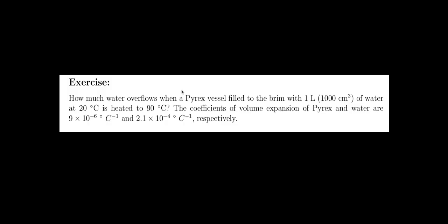Okay, so this exercise is for expansion of solids, liquids and gases. How much water overflows when a Pyrex vessel filled to the brim with 1 liter of water at 20 degrees Celsius is heated to 90 degrees Celsius? The coefficients of volume expansion of Pyrex and water are 9 times 10 to the minus 6 per degree Celsius and 2.1 times 10 to the minus 4 per degree Celsius respectively. So the question is similar to the example that we did.